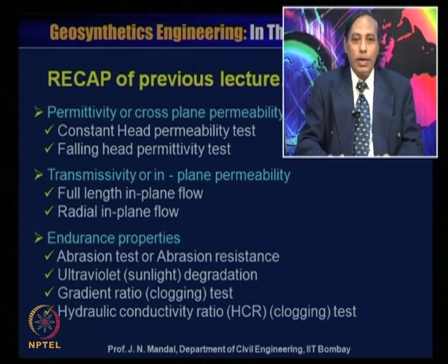Then transmissivity or in-plane permeability, that is under full length in-plane flow and radial in-plane flow. And next, endurance properties, that is abrasion test or abrasion resistance, ultraviolet or sunlight degradation, gradient ratio or clogging test, and hydraulic conductivity ratio, HCR or clogging test.